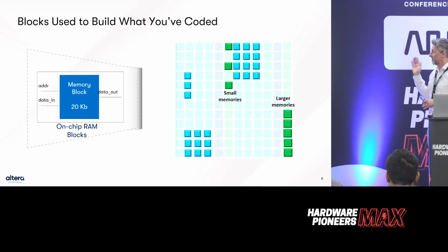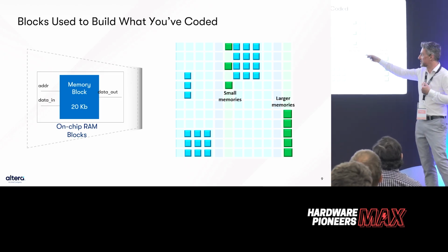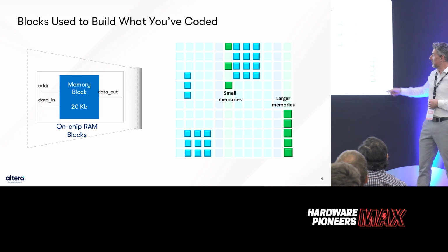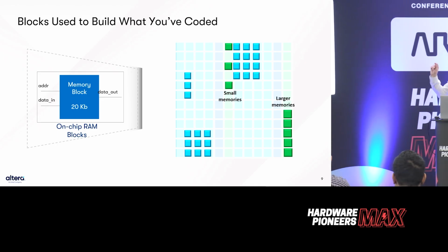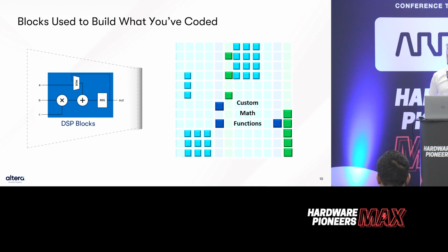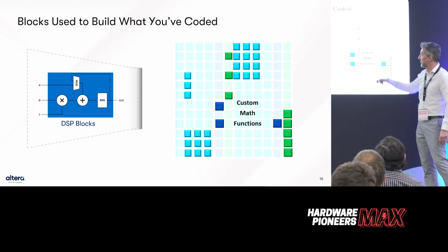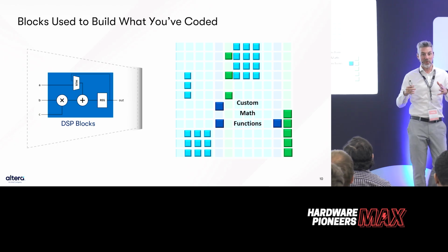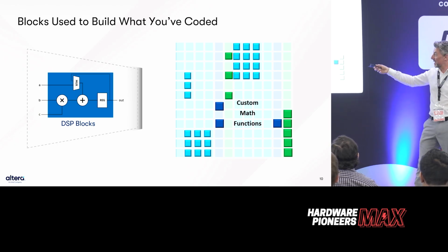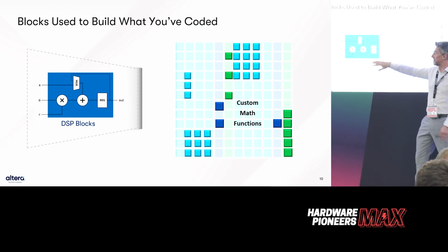The second basic building block is memory. So for us, we have small memories, 640 bits, placed around this matrix in the device, or larger memories on newer devices are all 20 kbytes each. So there'll be memory of some sort as well. So we've got the lookup table, the registers, memory, and then the other common primitive is DSP blocks. So you'll see those peppered throughout the whole device in various ways. Often in a column, there'll be repeating columns of DSP blocks. Usually they're built around like a multiply accumulate, so some sort of multiply, some adder, maybe another register as well. And these all come in different flavors. So some will have a couple of multipliers or a whole sea of gates in different ways for doing different functions.